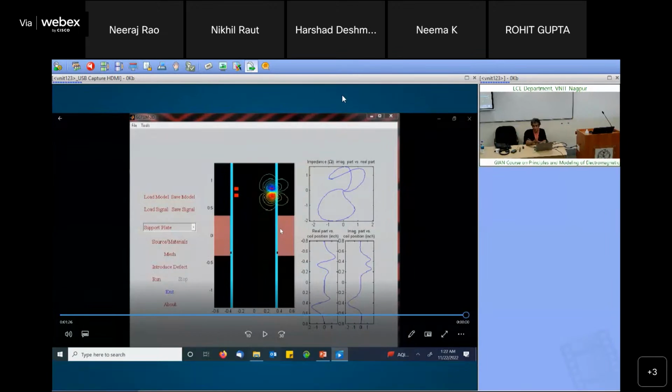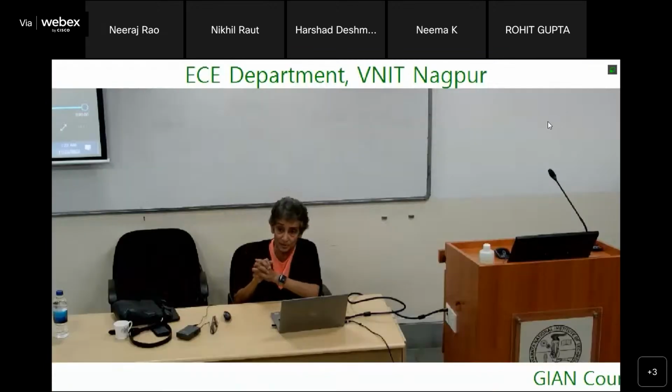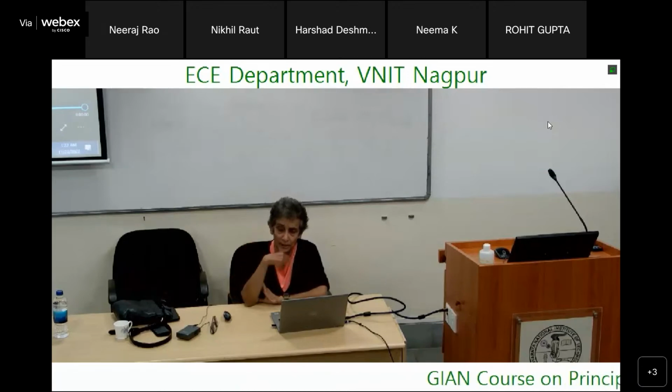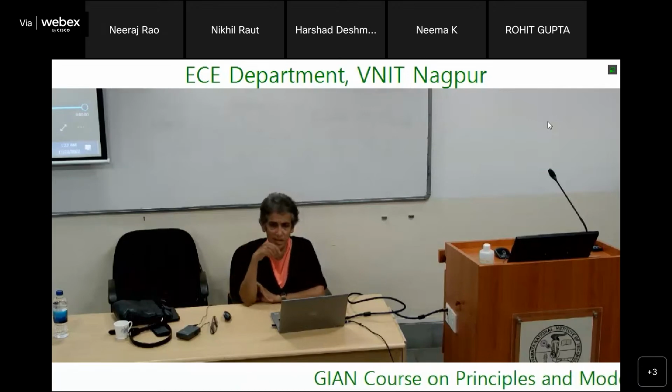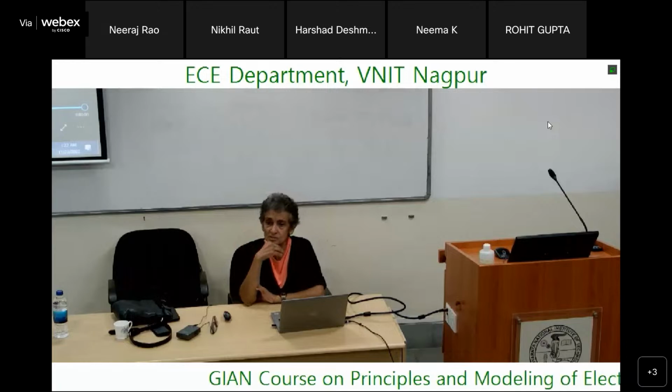So you have to do everything that we did. Eventually, that also results in a matrix equation. The way you get to the matrix equation is somewhat different. In a way, because I don't need too many small elements in the defect area, it is a little more efficient for modeling narrow cracks. For example, all I need is these nodes.